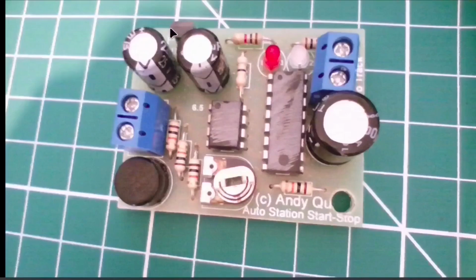There's a device up here which looks like a voltage regulator. These three resistors down here, these are 10k resistors, and that's a 10k resistor. That's a 1k, and that's a 1k. Brown, black, red is a 1000 ohm resistor. Brown, black, orange is a 10,000 ohm resistor.